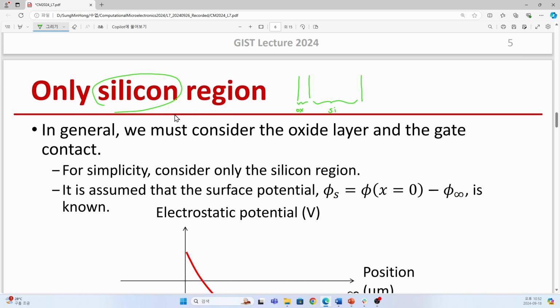It means that our discussion now comes back to that of lecture 4. In lecture 4, we considered only the silicon region, and under constant doping concentration, we integrated the weighted Poisson equation and got a certain analytic expression for the surface electric field. So that was quite good, and we are now doing the same job with numerical calculation.